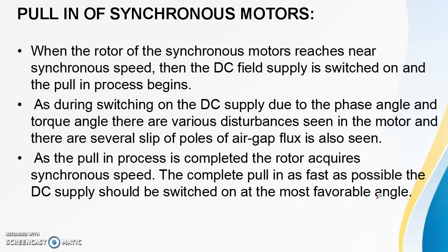As the pull-in process is completed, the rotor attains the synchronous speed. Once the pull-in process is completed, only then is the motor speed synchronized. To complete the pull-in as fast as possible, the DC supply should be switched on at the most favorable angle. This is the overall pull-in process of a synchronous motor.